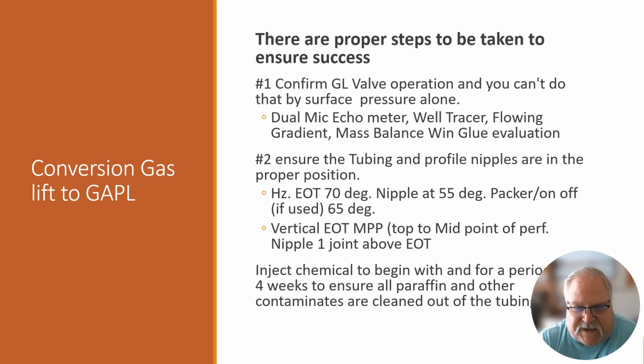What is the throughput at that? What do you think is the point? There are a lot of times where people are injecting 1 million standard cubic feet, or 28.3 E3, and then if you look at the size of the throughput and the differential pressures, the maximum capacity going through that orifice is 7 E3, and they're pumping 28 through, assuming that they're going down to that low point. Well, they're not. They're either multi-pointing, there's a hole, something's washed out, something's going on. So you need to know all this information to ensure that you're injecting at the right point.